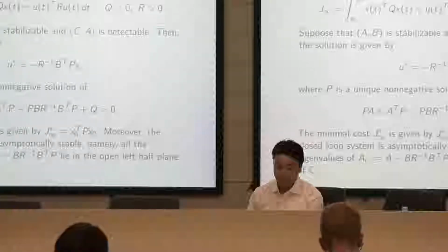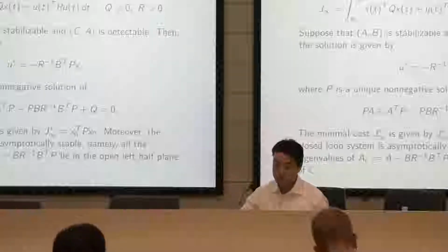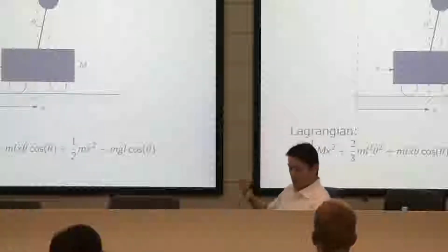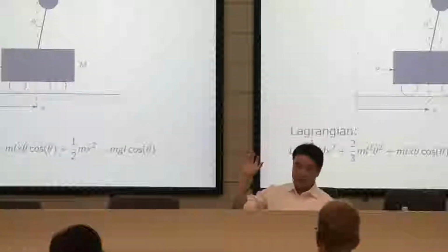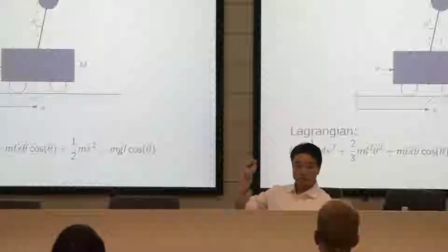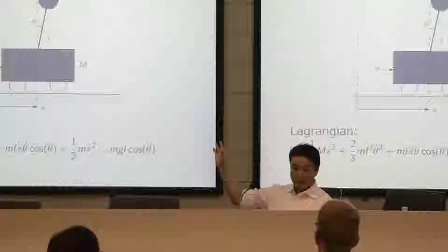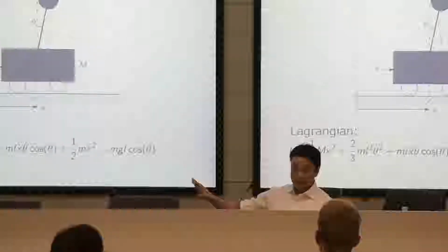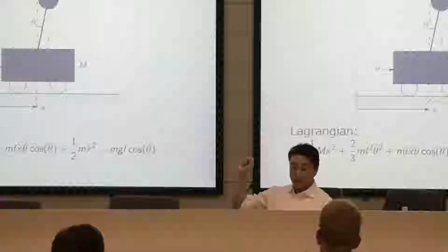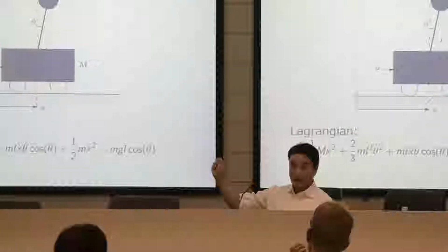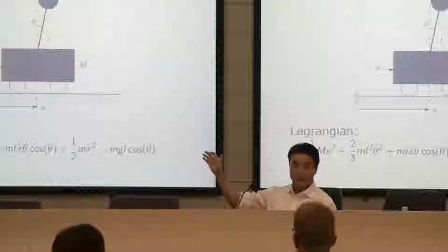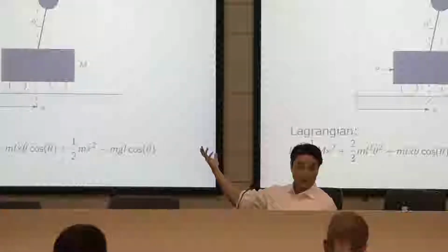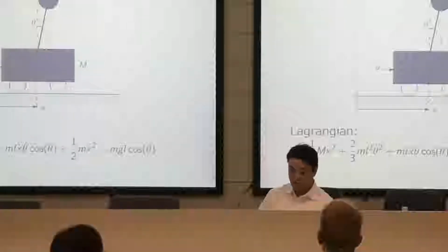And we're going to apply this to a simple mechanical system, the inverted pendulum. This material is very standard in control engineering departments, using this kind of mechanical system. Although this is nonlinear, we derive the system equation, find the equilibrium, linearize it and get A and B, and apply the algebraic Riccati equation and get the feedback control.